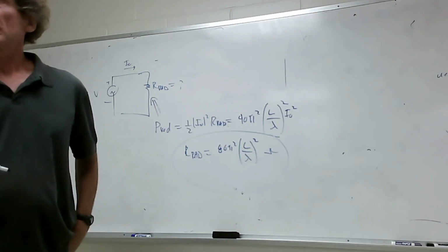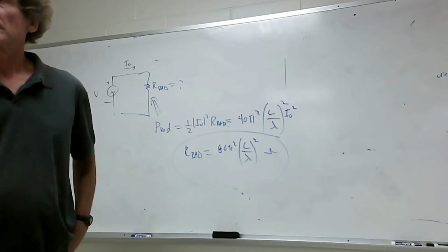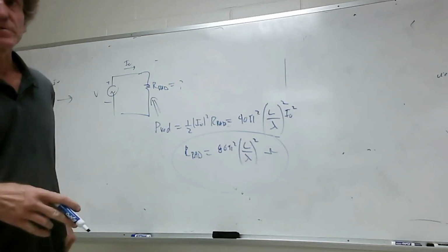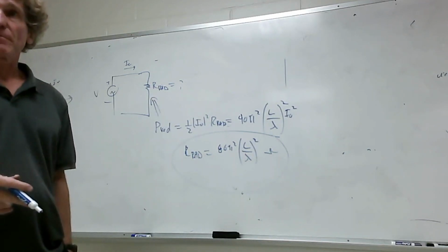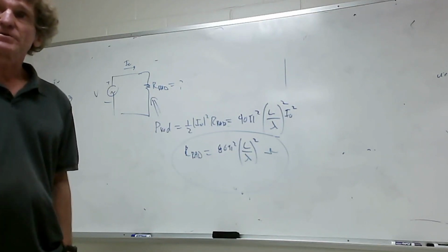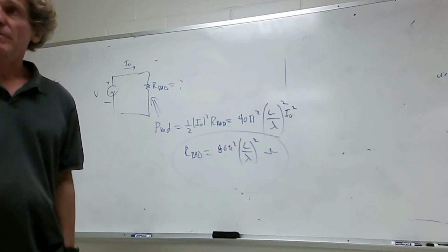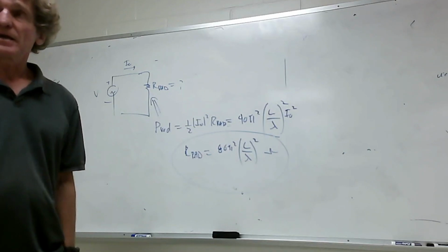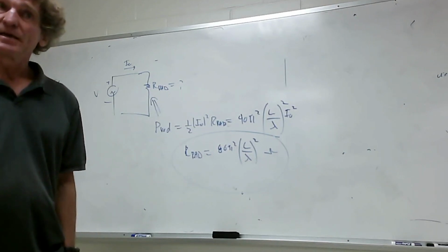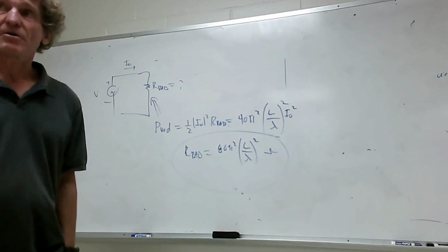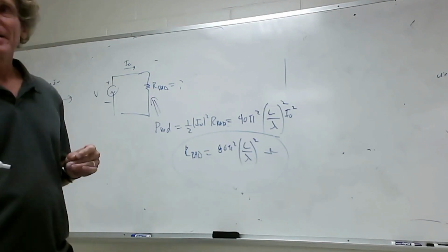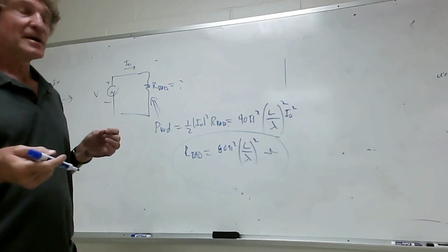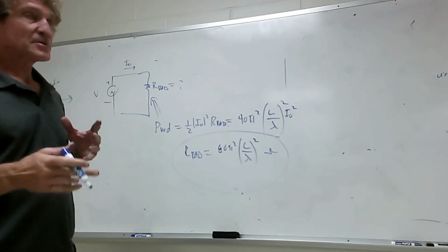So that would be a nuclear reactor. Now, or coal, that would be 500 combined cycle coal. And again, this is not my area of expertise, but I know they would like to have it at 1,000,000 volts or more. But the minute you get up to that super high voltage, you get what's called corona discharge around wires. And when that happens, you get a lot of power loss. And you can also get arcing. There's a lot of dangerous things that happen with real high voltage. Anyway, that's sort of the trade-off.